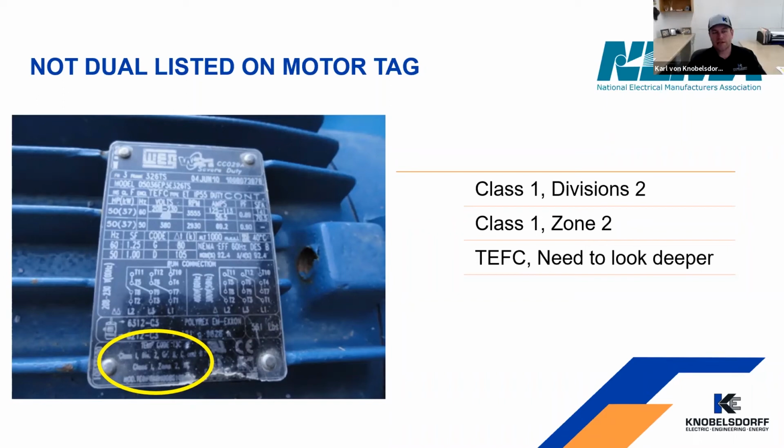So no nameplate. It depends if it's just a junction box or if it's on a listed piece of equipment. If it's a panel board or a panel on a piece of OEM packaging equipment, we would approach that a little bit differently. If it's just a pull box on a wall, if there's no nameplate on it, it's really going to be de-energizing any circuit that's in there, and then you're going to have to open it up and see if there's gaskets on there or if it's non-gasketed. Some of the older stuff is hard if there's no listing on there. We don't know who manufactured it, so you can't go back to figure that out.